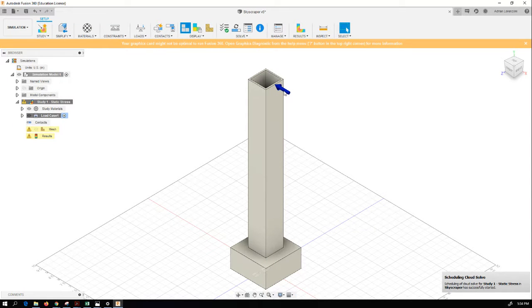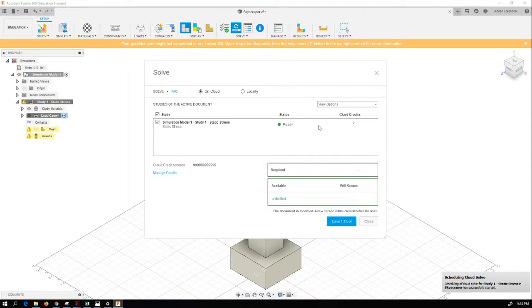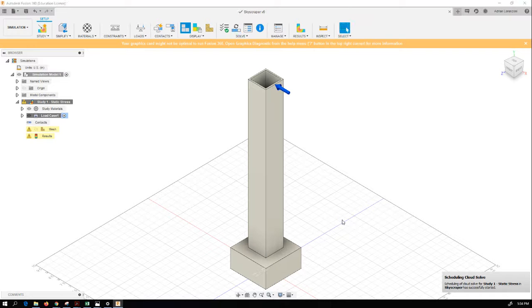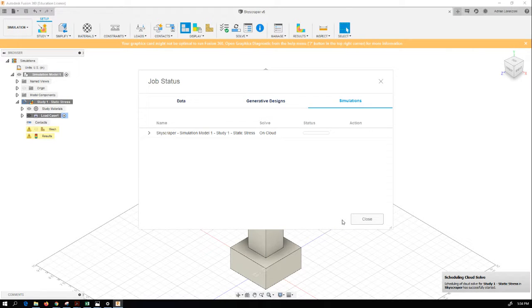And then solve it. So this is good. What did we just decrease? We just decreased the moment of inertia, by what I think is going to be a good amount. That's going to affect the stress, because the larger the moment of inertia is, the less stress we're going to have, which in turn affects the strain, deflection, etc.